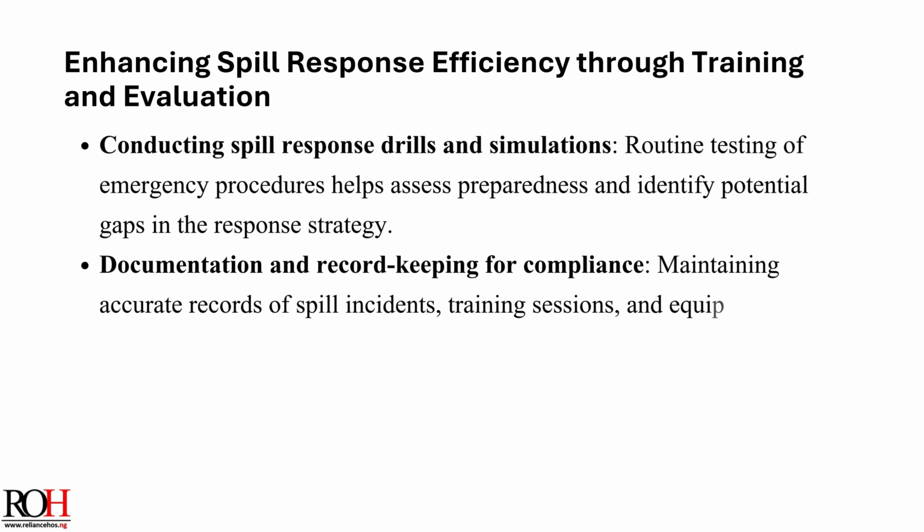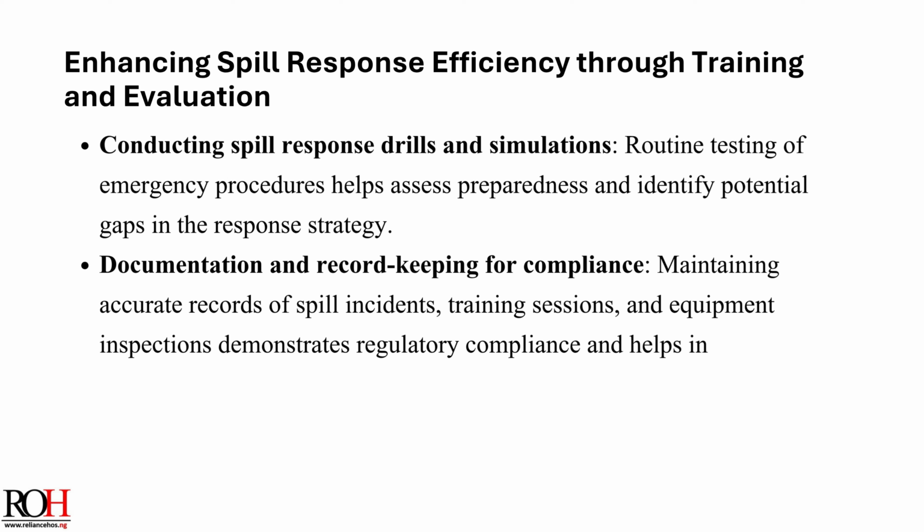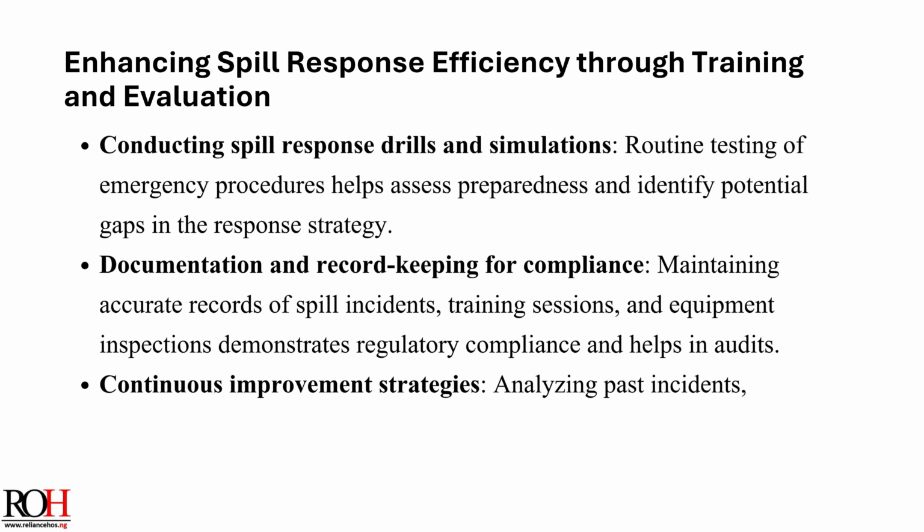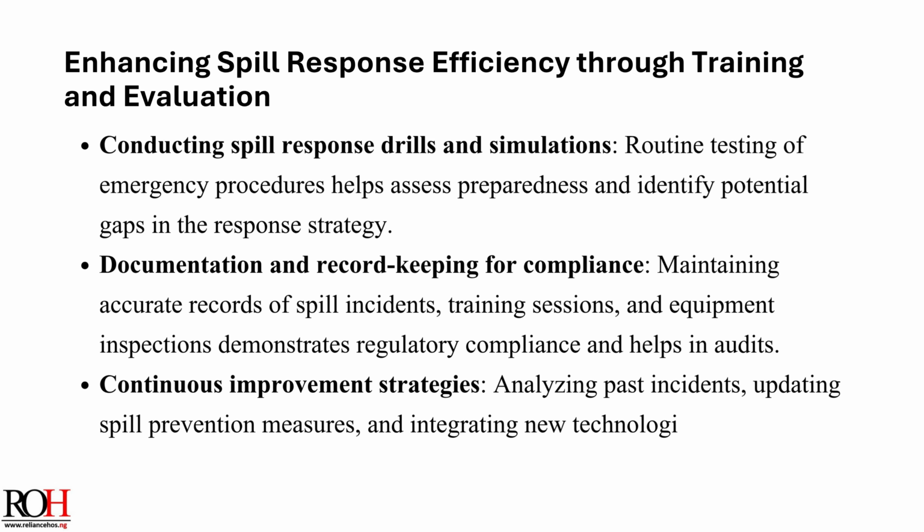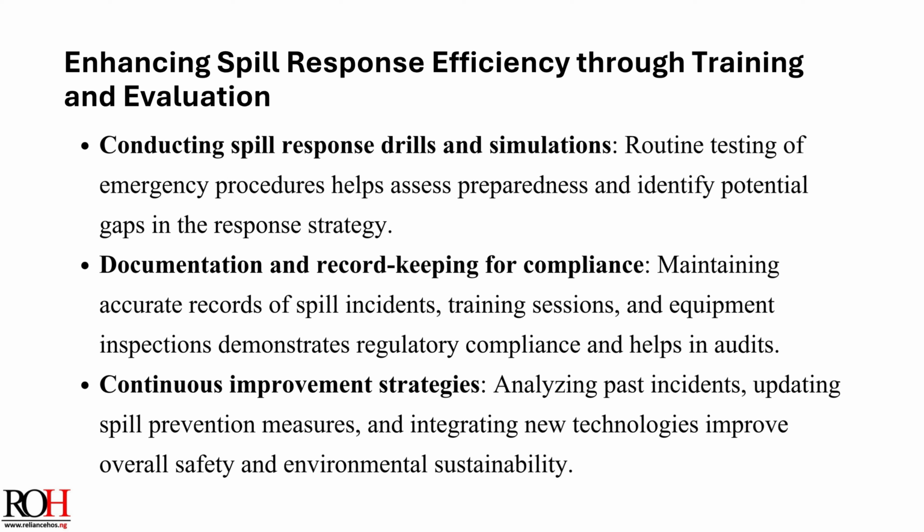Documentation and record keeping for compliance. Maintaining accurate records of spill incidents, training sessions, and equipment inspections demonstrates regulatory compliance and helps in audits. Continuous improvement strategies. Analyzing past incidents, updating spill prevention measures, and integrating new technologies improve overall safety and environmental sustainability.